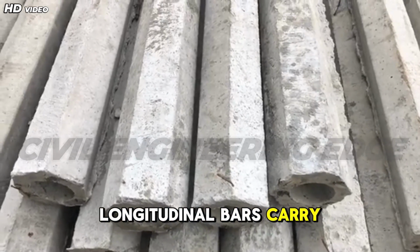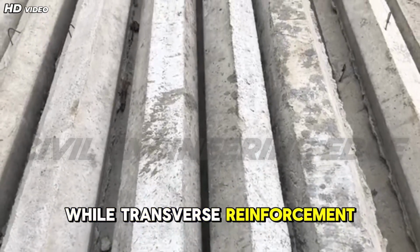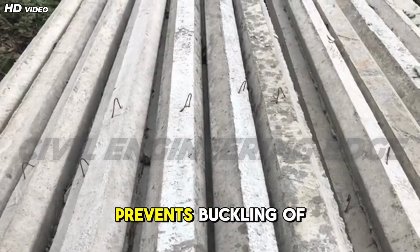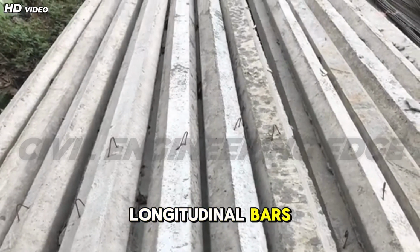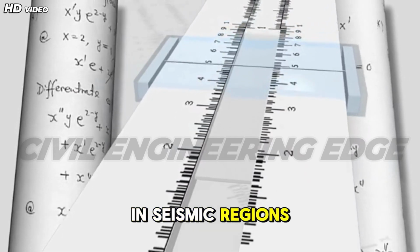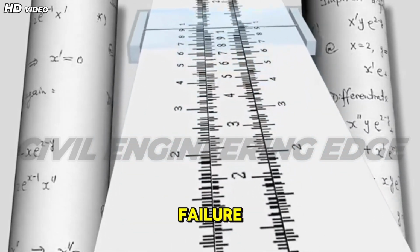Longitudinal bars carry axial loads and bending stresses, while transverse reinforcement such as ties or spirals provides confinement, prevents buckling of longitudinal bars, and enhances ductility. In seismic regions, closely spaced ties are essential to prevent sudden brittle failure.